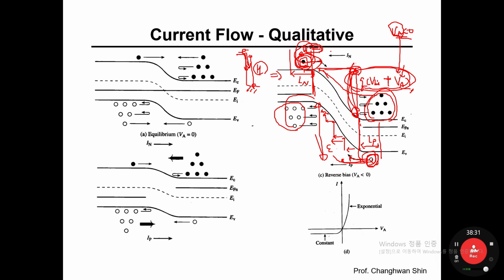So similarly, for this given energy band diagram, how much reverse bias has been applied is nothing to do with how many electrons would be injected into the depletion layer. The key factor in determining how many electrons would get into the depletion layer width is the diffusion length.